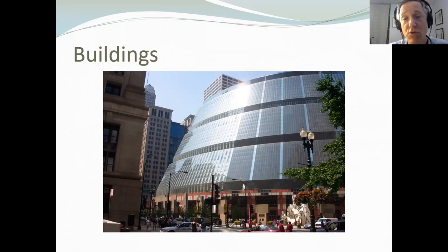So generally it's a cooling problem. You're trying to keep buildings cool. What you don't want with cooling is big giant glass surfaces. It's great for residential, and on a cold day it's all good for residential. Passive solar is wonderful. In commercial buildings, a whole different world. You want windows that do not emit light, plus the embodied energy of glass is high.